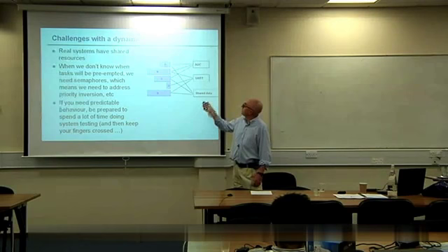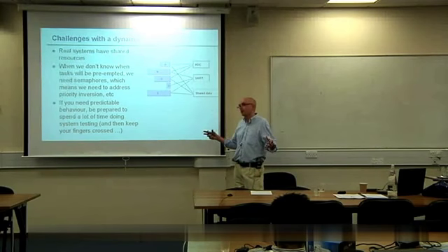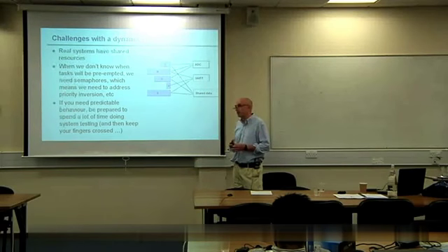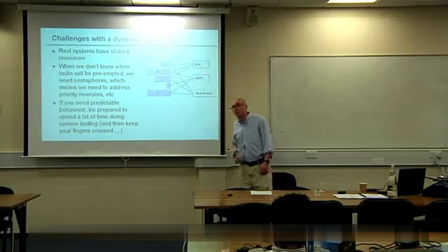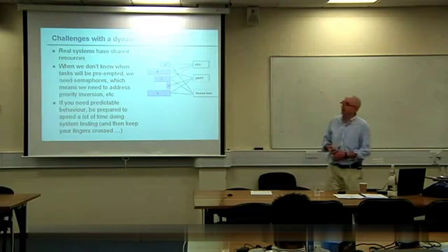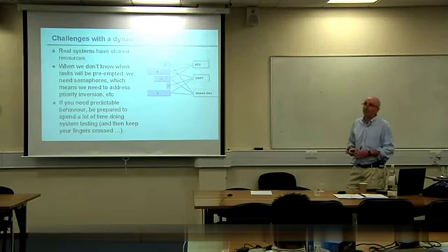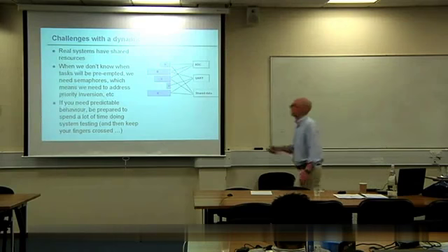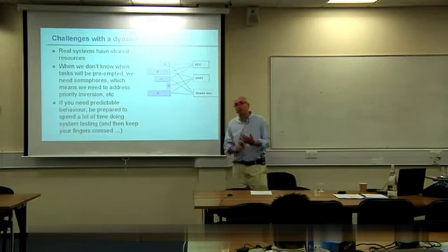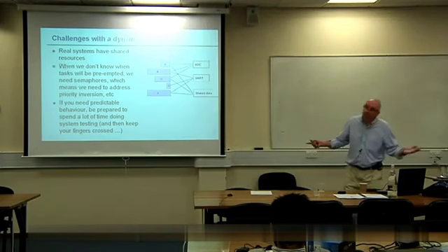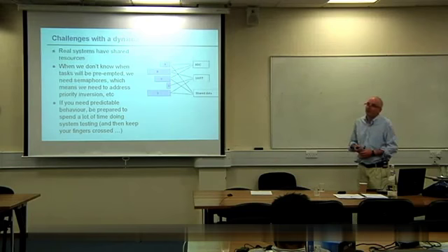Many times, you can actually statically design the system so that you are pretty sure in advance that these conflicts won't happen. Then at runtime, you check. So before a low priority task accesses a resource, it checks with the schedule and just double checks to make sure that it does have time to access that resource. If not, it suspends and ensures that the high priority task that's doing your data sampling, which must be done with a 0.1 microseconds, etc. time constraint, will run. And you can guarantee, absolutely guarantee, that that will happen.